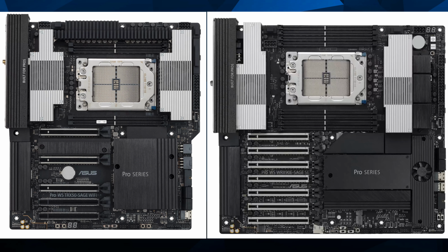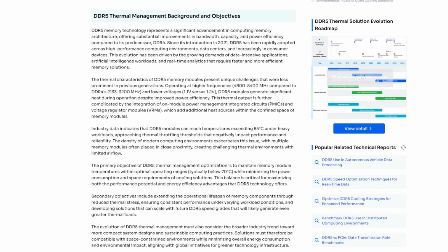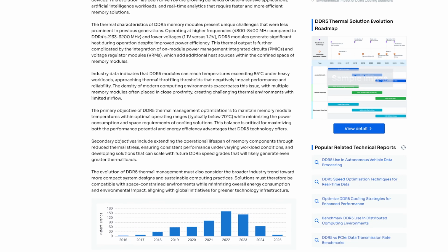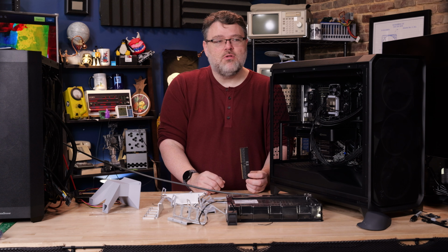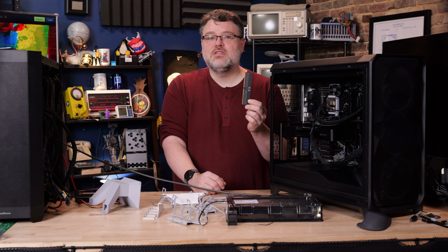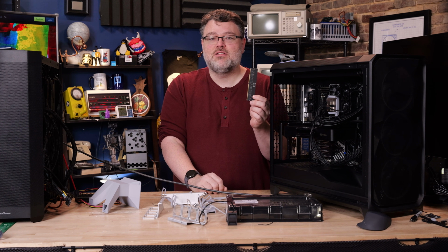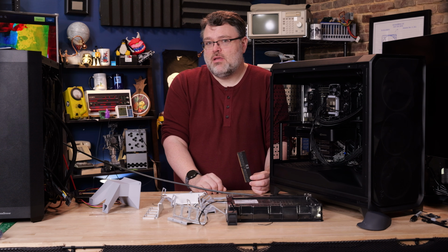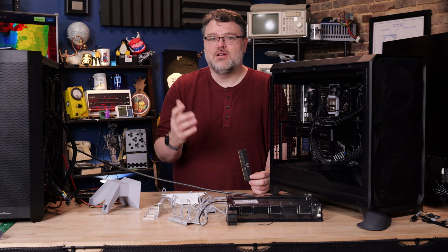But the assumption on all of this is that throttling actually works. Throttling is a totally new feature of DDR5. It halves the memory clock in thermal constraints, or at least it's supposed to. It prevents thermal runaway from damaging the DIMMs, because these will happily get to 140 degrees C until they fail catastrophically. If it's not working, the hardware can die in those scenarios, in other words.